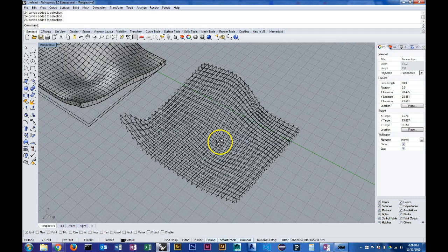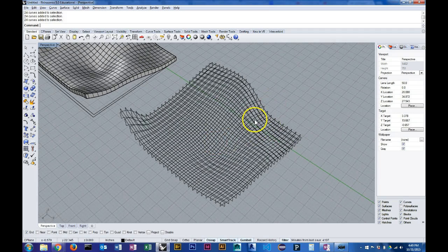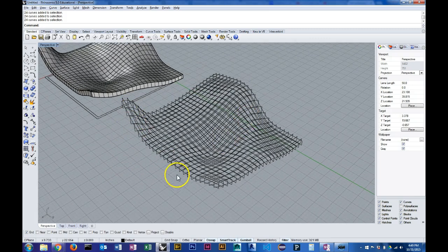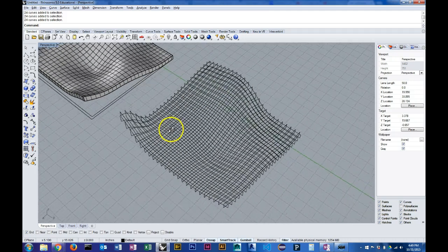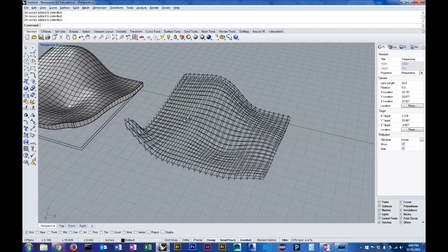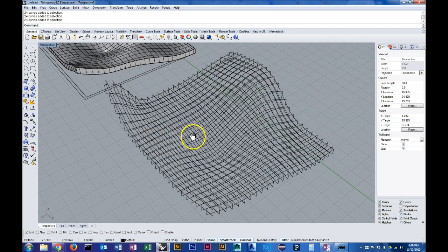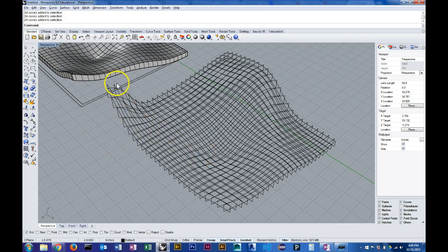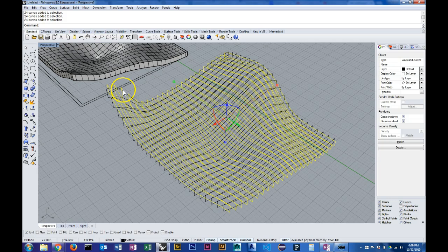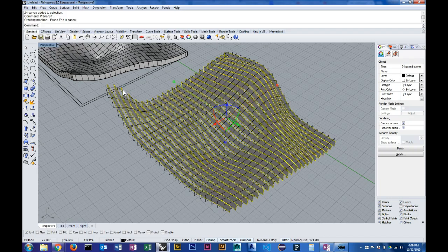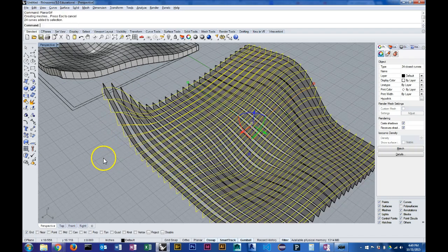So to start, what I want to do is come up with geometry that will help me locate the notches that indicate where they're going to fit together. So one way to do this, I'm sure there are multiple ways, the way that I've been doing it is if I select these ribs, since they are planar cross sections, contours of my model, I can use the planar surface command to turn these into surfaces. And I'll do that for the other direction as well.